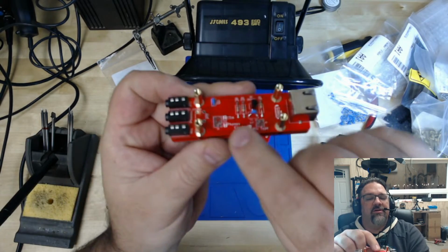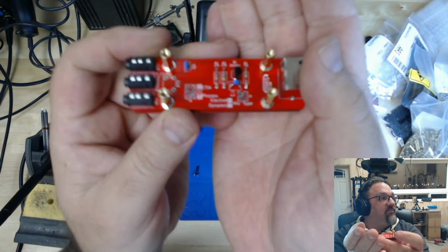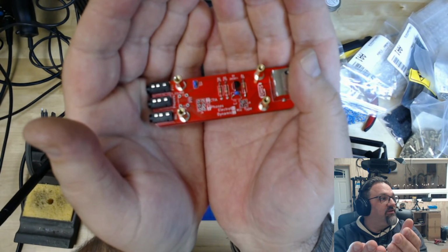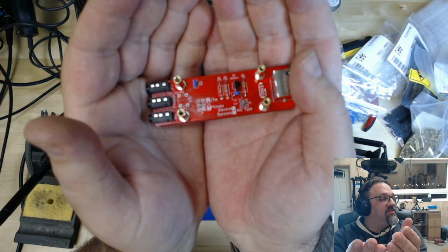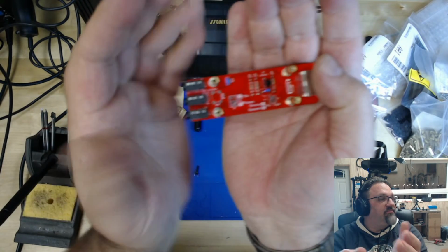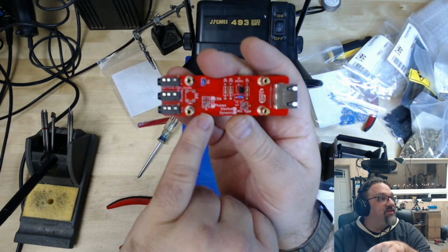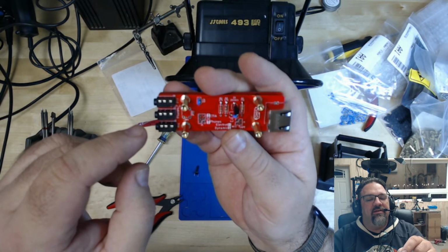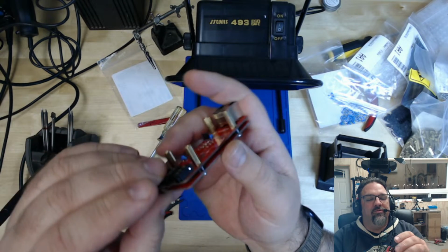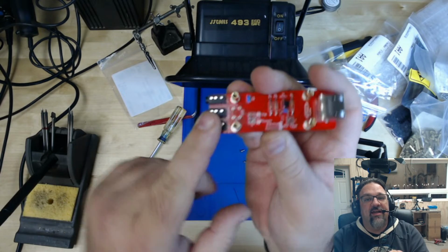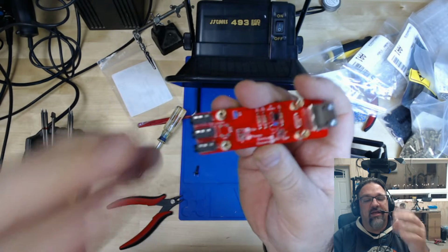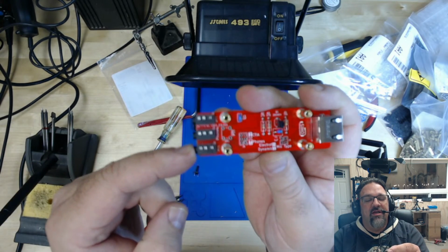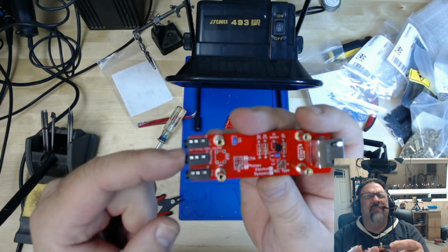Yeah. So these three jumpers over here, let's see here, can I make this focus? I don't know. Is it going to do it? Come on. Be nice. No? Jerk. Anyway, those jumpers, you put the two jumpers on that side, and I think either the phones or the mic or both turn into a 4-pin CTIA. Left, right, ground, and then mic. Whereas if you pull it down to the bottom, then it's just headphones, and then the mic is separate. So I guess it is the headphones that becomes the CTIA plug.